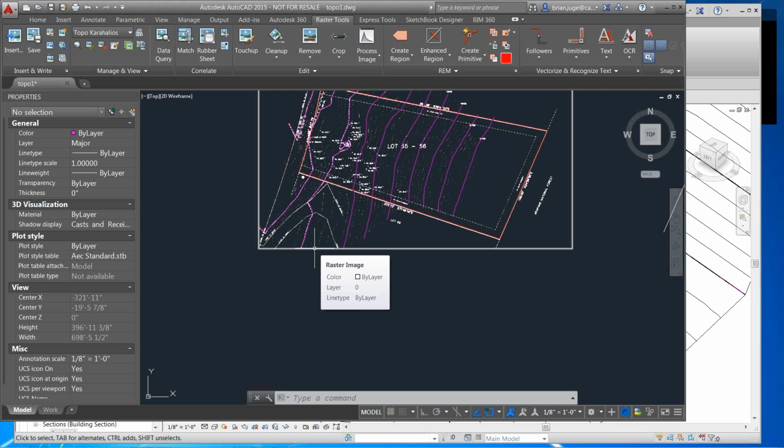the origin point where it's located, that you're limited to 20 miles, really you're limited to 2 miles from the origin point, and then Revit just doesn't work. So what we can do is have them give us a property line or something that's close. If you don't have some known datum that they're going to consistently use, have them put a point that you can use as origin to origin, somewhere near where your site is. If you could just have them provide that one element, then we can make that the origin point in AutoCAD and redefine that when we go to bring in their CAD files over and over again.